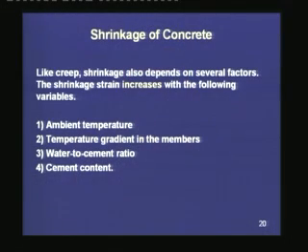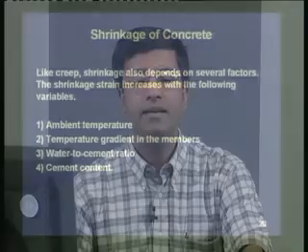Now, like creep, shrinkage also depends on several factors. The shrinkage strain increases with the following variables. Ambient temperature. If the temperature goes up, then the loss of moisture is rapid and the shrinkage strain goes up. Second is the temperature gradient in the members. If the temperature gradient is high, then we observe that the shrinkage will be also high.